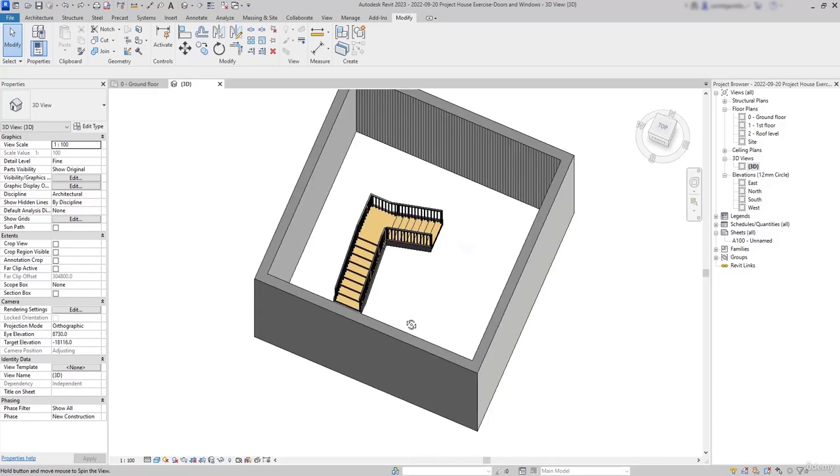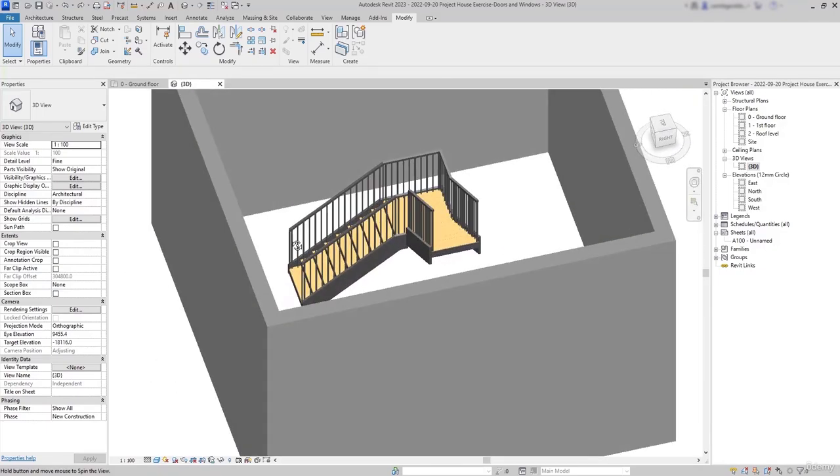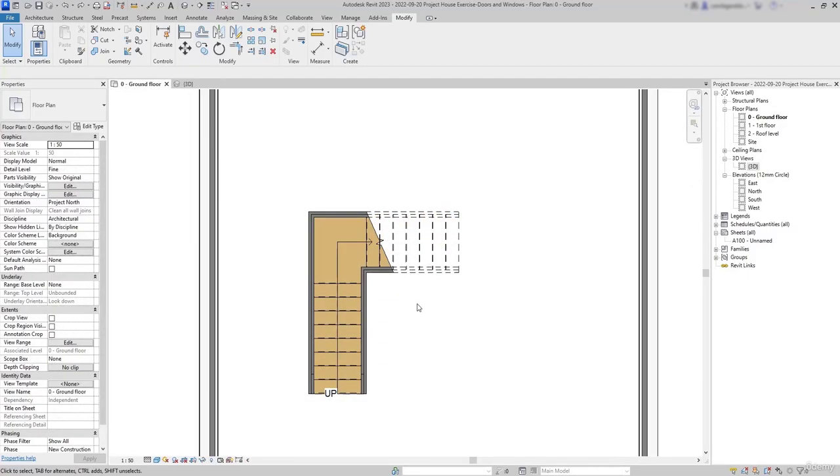It's this. As you can see, I started drawing from the ground floor, and the top part is exactly at the first floor level. Let's go back to the ground floor, and now I'm going to select the stair, and this may be a bit tricky to understand in the beginning. I'm going to move the pointer towards the inner side, and as you can see, everything highlights now.